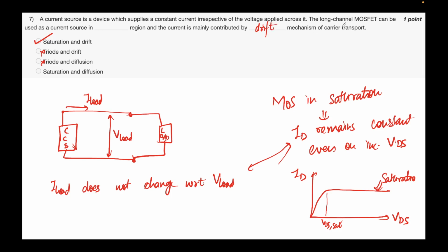So this is the application of the MOSFET, where it's actually practically used when you make a constant current source. It's not just only a MOSFET; there are other things to control the voltage and so on. For instance, you want ideally VDS sat to be as low as possible, because remember, it's a constant current source in saturation only after VD is greater than or equal to VDS sat. So you want this voltage to be as low as possible, as simple as that.